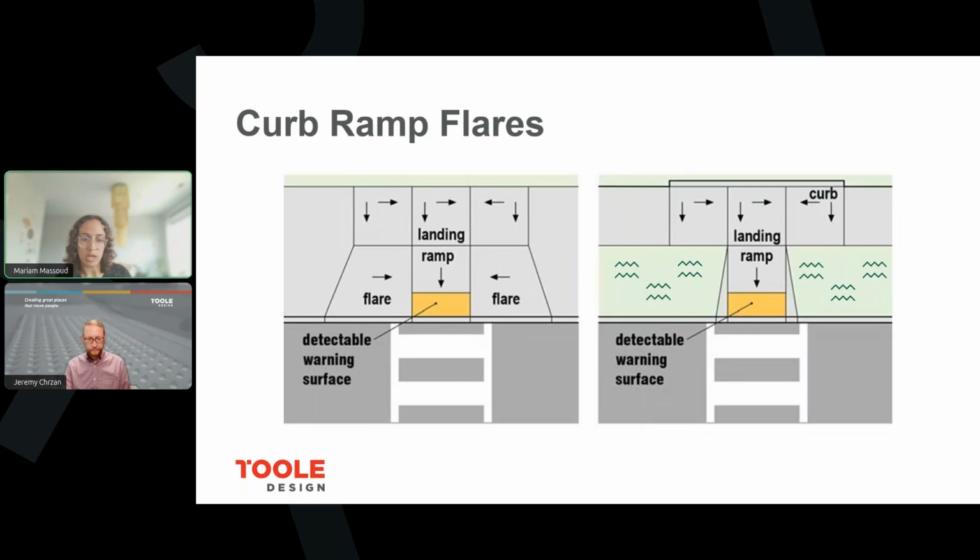So this is what we were talking about earlier, how they're not always required. On the left, the ramp is next to sidewalk, so the flares are required. In the image on the right, we have the grassy area shown with zigzags in green color. Because that grassy area is not walkable, flares are also not required.